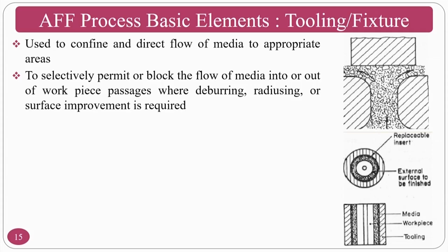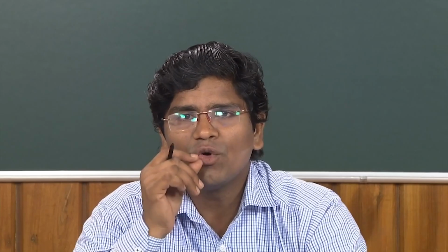Also, to selectively permit or block the flow of media into or out of workpiece passages where the deburring, radiusing and surface improvement is required. That means it has to permit flow only to the regions where it has to finish. It should not go into the other regions.